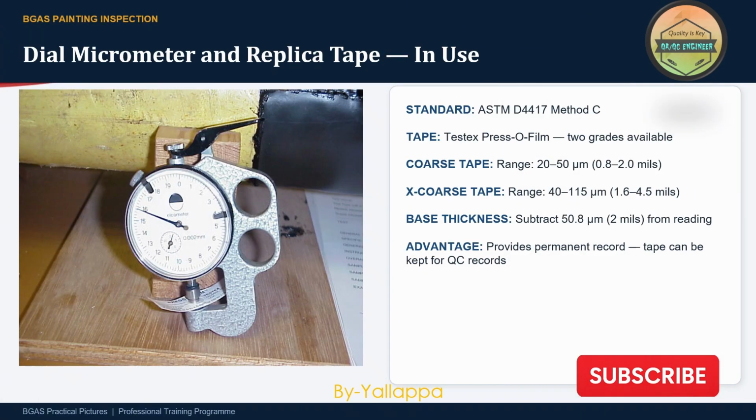This slide demonstrates proper replica tape application. The tape must be firmly burnished against the blasted surface using the supplied tool. Insufficient pressure can result in inaccurate readings. Inspectors should take multiple readings across the surface and record the average value. Consistency is essential when verifying compliance with project specifications.